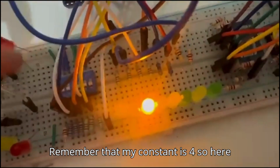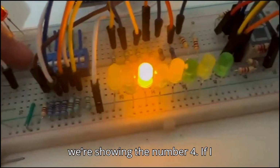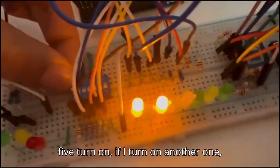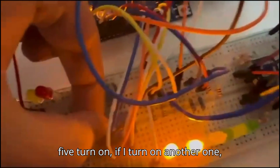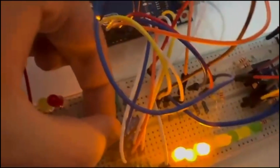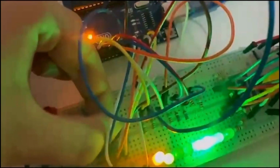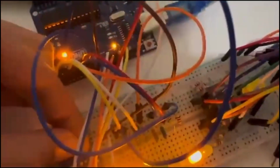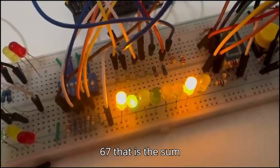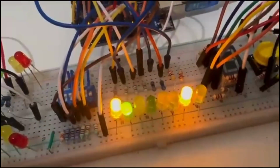Remember that my constant is 4, so here the DIP switch is off and we're showing the number 4. If I turn on one of the DIP switches, 5 turns on. If I turn on another one, it's 6, and it continues like that. I'm going to turn on all of the DIP switches, and here we can see 67. That is the sum from my DIP switch, and it's shown by the LEDs.